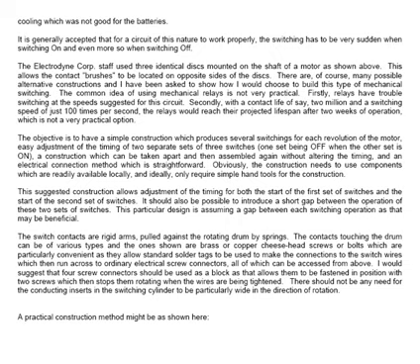The objective is to have a simple construction which produces several switchings for each revolution of the motor, easy adjustment of the timing of 2 separate sets of 3 switches, one set being off while the other set is on, a construction which can be taken apart and then assembled again without altering the timing, and an electrical connection method which is straightforward.